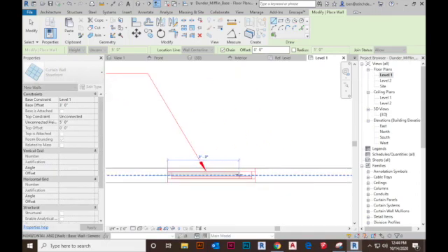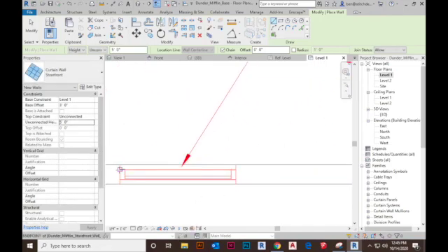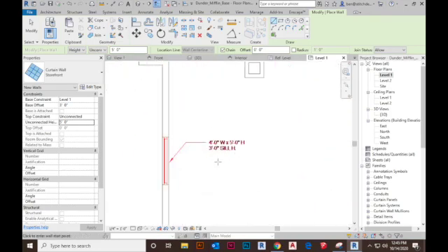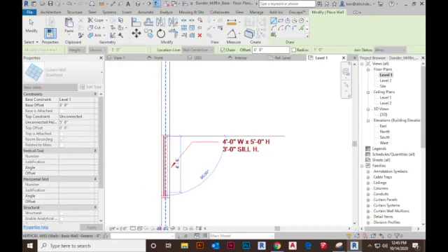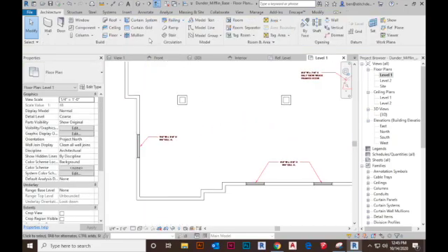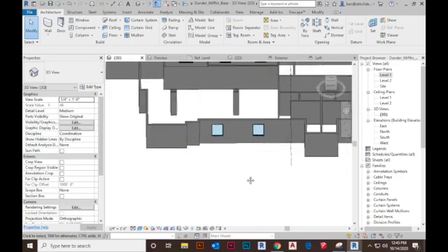You can also see that I'm drawing that glazed panel offset to the top of where our CAD layout is. To flip or mirror that in place on that center line, I just hit my space bar and it will flip that down to the correct offset. Looks good.